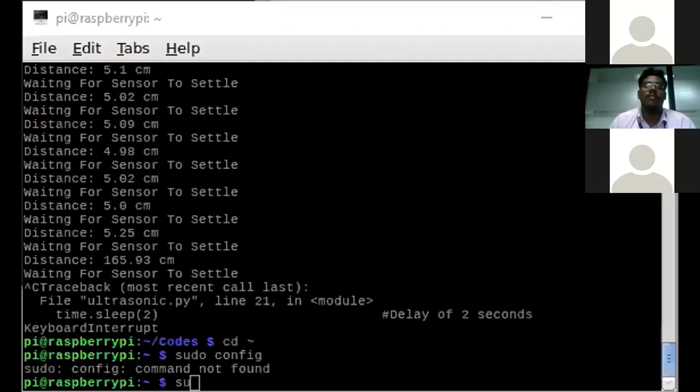For the temperature sensor, for low precision we use LM35, for high precision we use the Omron thermal sensor. So based on the purpose we can use either. The magnetic sensor is one of the digital sensors. It acts as a magnet, so north and south poles attract each other. When the switch closes, the value will be 1. Open means 0. So based on the purpose you can use it.